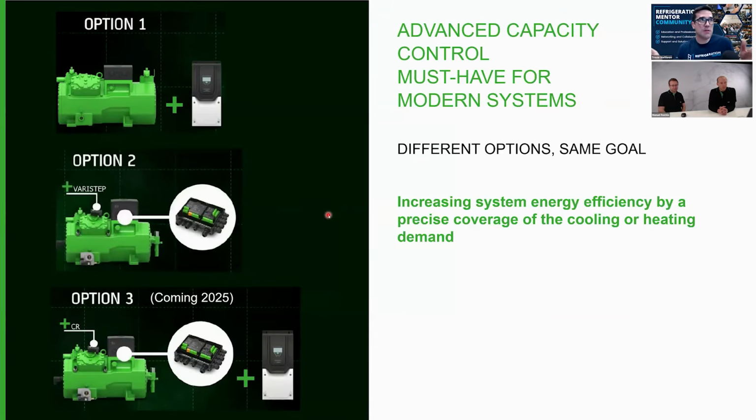So now we're saying that, because we know the compressor can go down, I think to 25 hertz at most. It differs depending on the model. You always have to check the application engineering, or go to the Bitzer web software and look, because different compressors have different ranges. For this one, for example, it would go to 25 hertz and then potentially use unloaders, or do one or the other. This is pretty cool. I'm loving seeing this. This is definitely making me intrigued, and I have so many questions already on that one. Excellent. We have to have a separate session on that. Yeah, that's for sure. I love it.